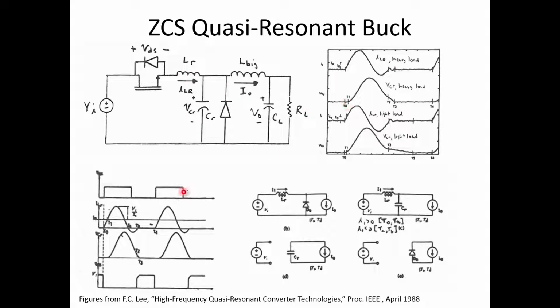Because, I should have been clear, this rings up, VCR peaks, and then VCR rings down to zero, and the diode picks up the current. So what happens is I have a situation where this diode's carrying the output current, except for pulses when I trip this device on. And depending upon how often I trip this device on, I get more and more pulses from the input.